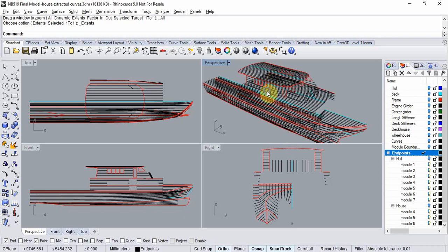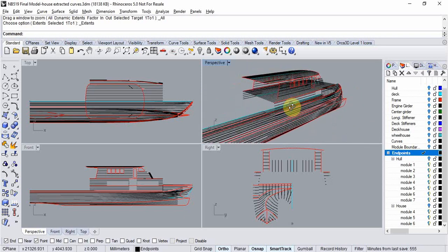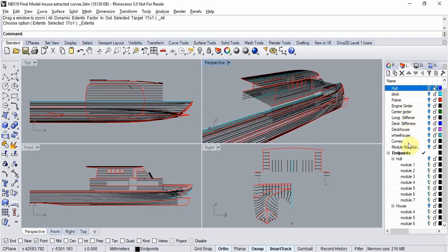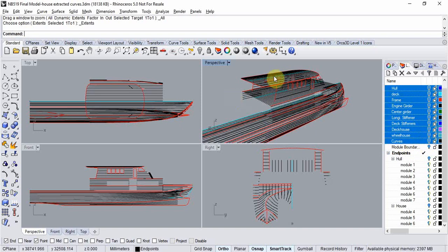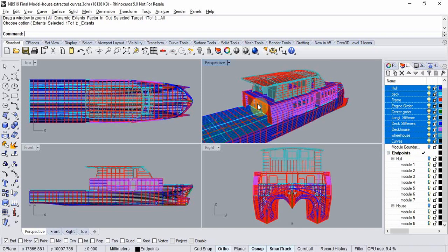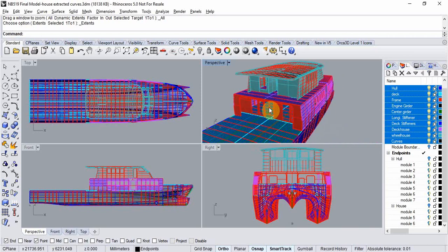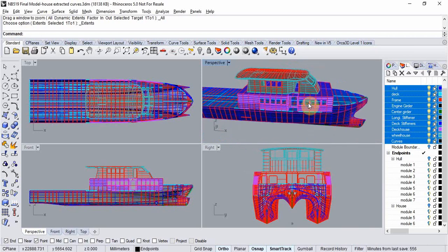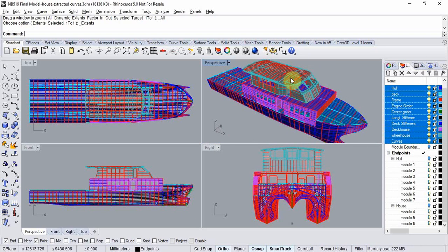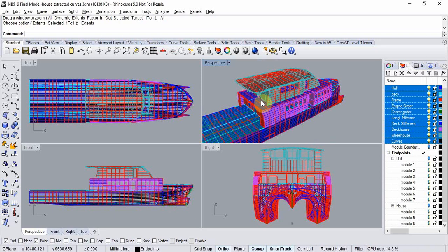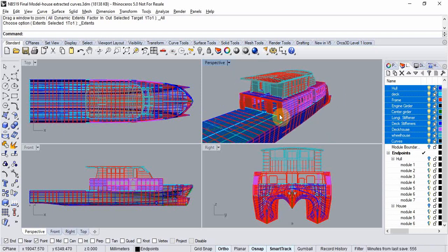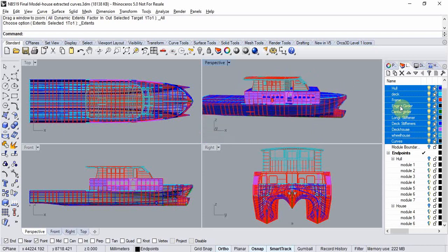Initially, looking at the superstructure, it appeared to be asymmetric, so I thought we would need to model the whole thing. But if we take a closer look, since all of the longitudinal structure defined by these endpoints appears to be symmetric, we can see that the asymmetries appear to be limited to the transverse bulkheads. This should allow us to also model just half of the superstructure with the endpoints and strakes. And once we create our reference nodes in Maestro and import them back into Rhino, when we build our transverse bulkheads, we'll simply build the full width of the bulkhead with all of the asymmetries included.